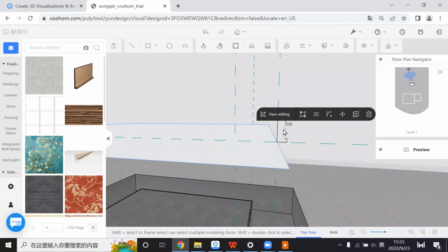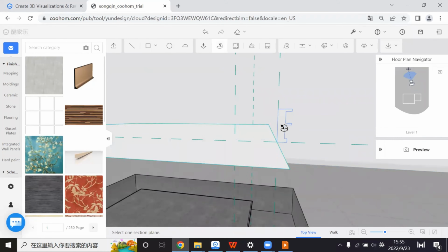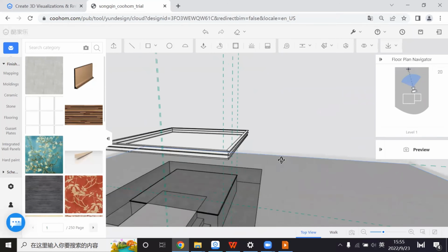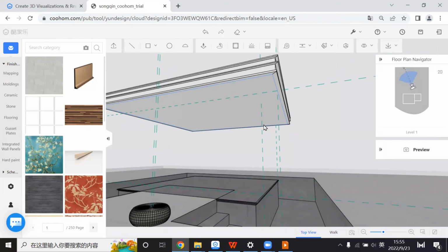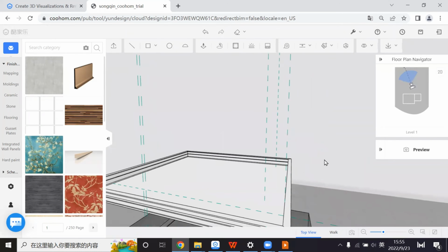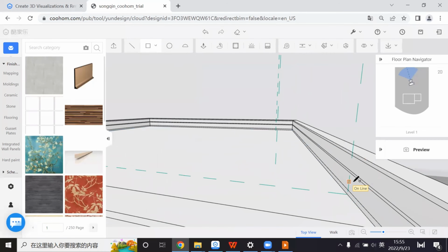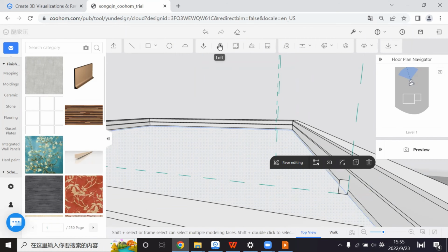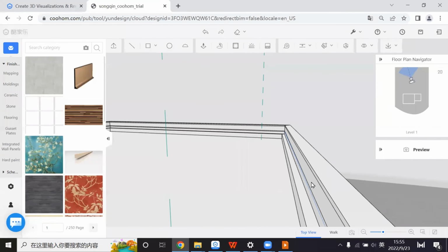Now click the roofs. Let the shape go around it by using this loft. First click the roof, then click the loft and click this surface, and now you can have that. See that? You can directly have this shape. The same thing happens if you want to draw out internally. For example, here you still want to draw out something, you can continue to draw. Hold, loft. See, continue by using this edge.